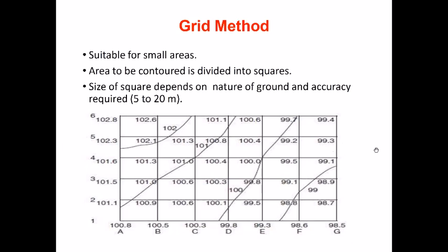So once you have chosen these values, then it depends on you to trace out on the entire map where that value could be. So let's say I'm trying to draw a contour for 102. Let's start from here. Now, if you look at these, over here the value is 98.6, over here is 98.8. That means no value between them will be 102.